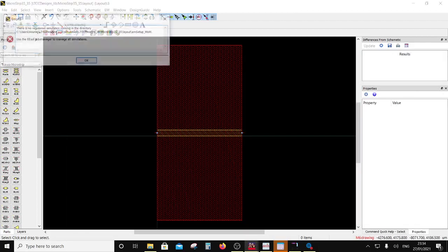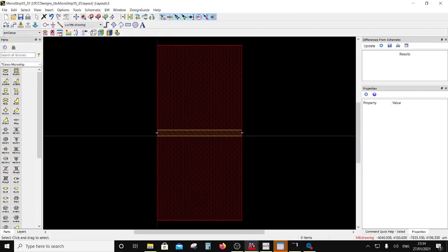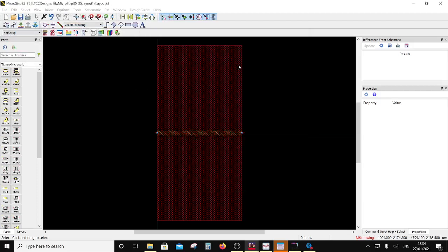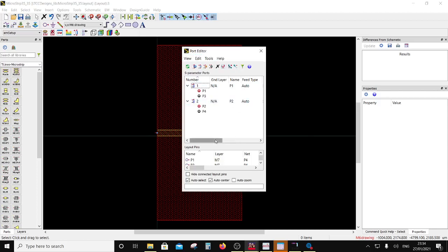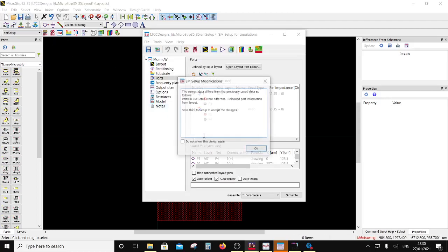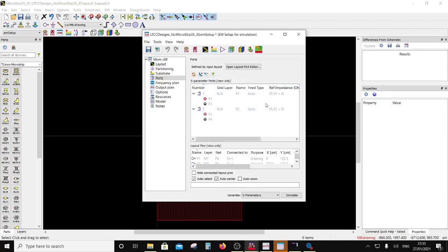It's just that in the port definition, sorry, in the port definition you should have put 35.35 here. So edit port and put here 35.35, 35.35, and that will be the center of the Smith chart, right? 35.35. That's the center of the Smith chart. Correct. So that's done. Go back and verify if that change has taken place.